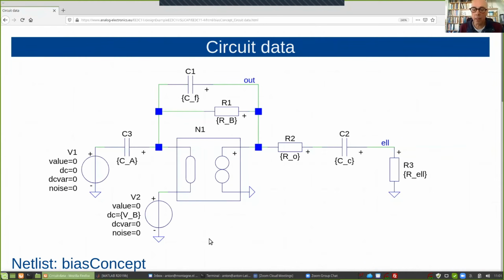And if we supply it between, for example, 0 and 5 volts, then the output cannot swing below 0 and above 5. So let's say if we have 5 volts, then you would like to have this operating point here at 2.5 volts. And that's what you do by lifting up this pin to 2.5 volts. So that is VB. So basically, in this case, you find VB at the output, and this DC current path provides it.